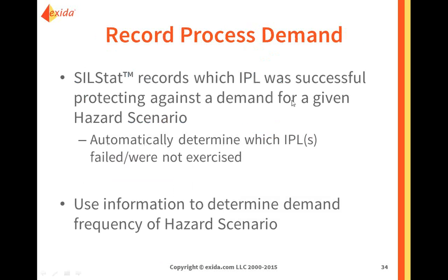And then one of the things that I forgot in this slide set is maintenance activity. So I already mentioned the sensing element in the toxic gas detector. We could have a maintenance activity scheduled every 3 months, replace that sensing module. So that's also something that you want to keep track of and that you want to perform in order to make sure that you comply to your original conceptual design.